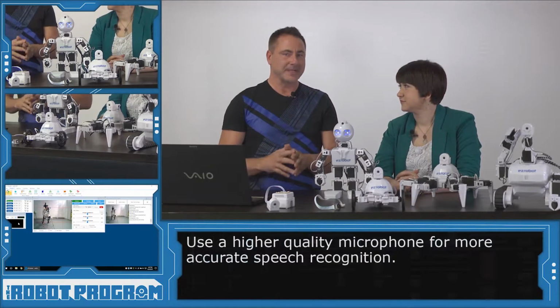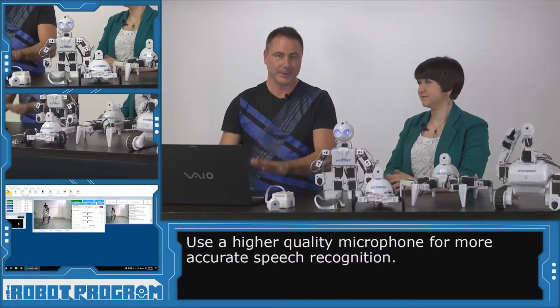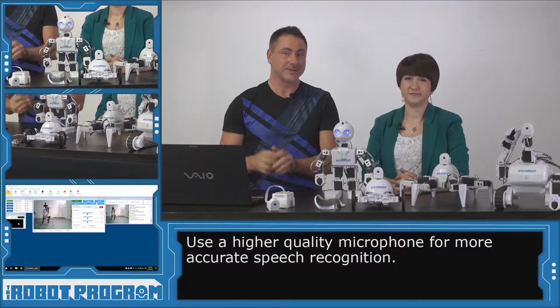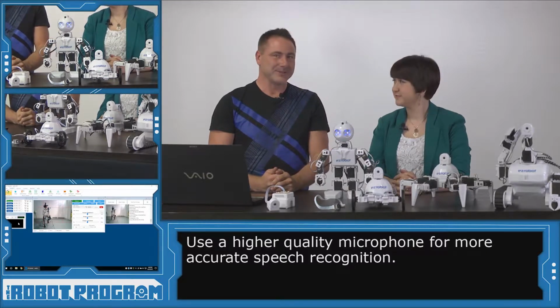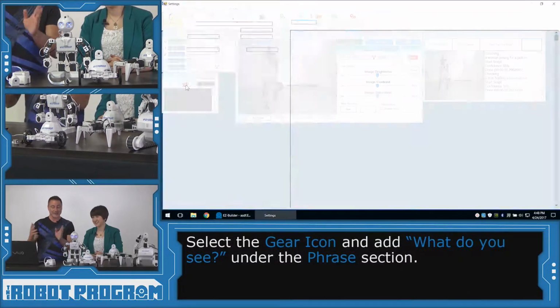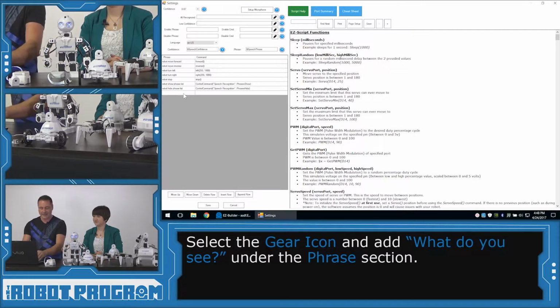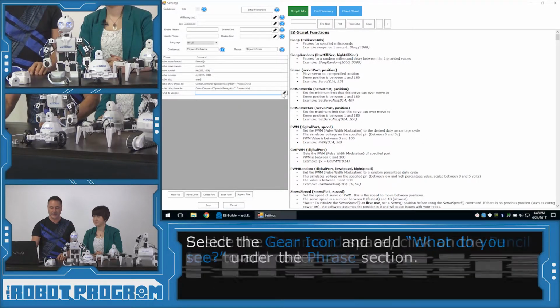Now, Easy Robot recommends using a real microphone, not the microphone built into your computer, because those microphones are usually not the greatest. And we might run into some trouble using that microphone. So this is a good demonstration of why you should use a real microphone. Worst case scenario here. That's right. So we're going to push the gear button on the speech recognition, and we're going to type in the phrase that it's going to detect. And that phrase is going to be, "What do you see?" And for the code, we're going to click on the little pencil.